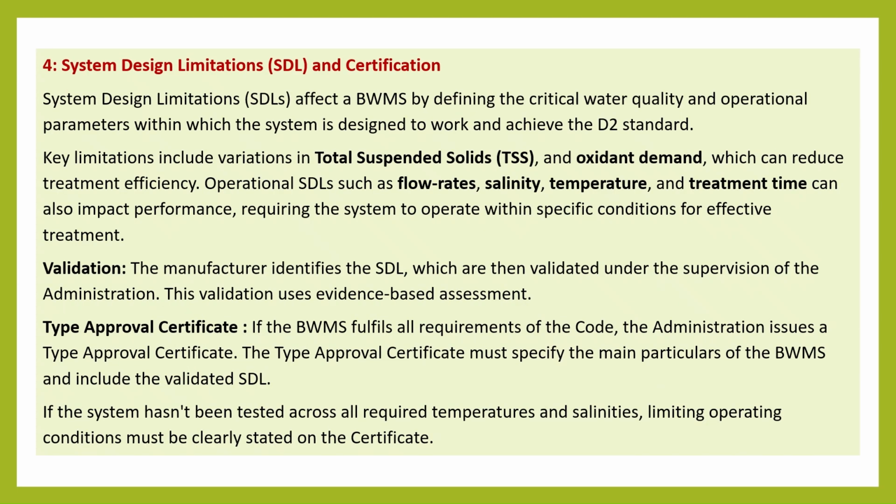System design limitations, SDL, and certification. System design limitations, SDLs, affect a BWMS by defining the critical water quality and operational parameters within which the system is designed to work and achieve the D2 standard. Key limitations include variations in total suspended solids, TSS, and oxygen demand, which can reduce treatment efficiency. Operational SDLs such as flow rates, salinity, temperature, and treatment time can also impact performance, requiring the system to operate within specific conditions for effective treatment.